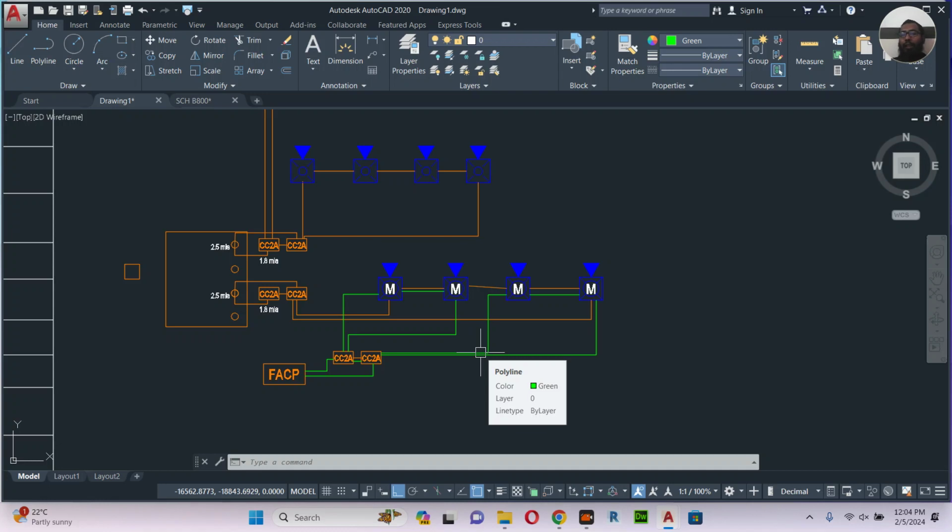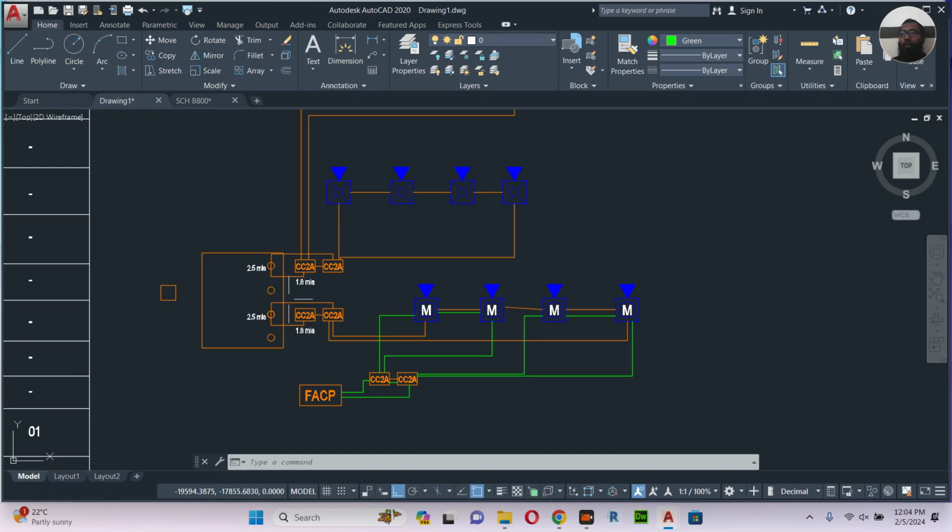There is another interesting thing. This auxiliary power supply, that means APS panel, will do more things. What? Let's say we have a mimic panel. What is mimic panel meaning? You will see inside the building there will be a board with the building plan and with small LED light. So when the fire happens, this mimic panel will indicate which area we have fire. So there will be a light, it will blink in the particular area. The fire alarm specialist, they will make the programming that you have to give